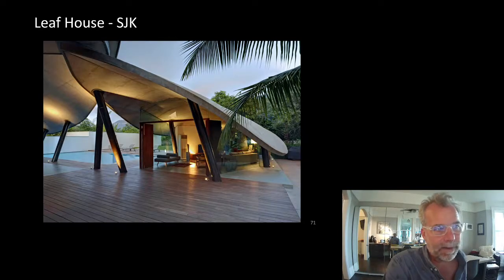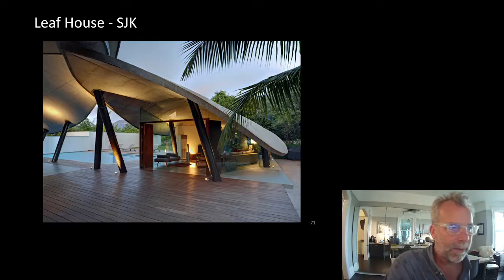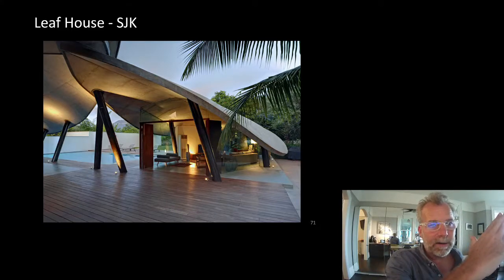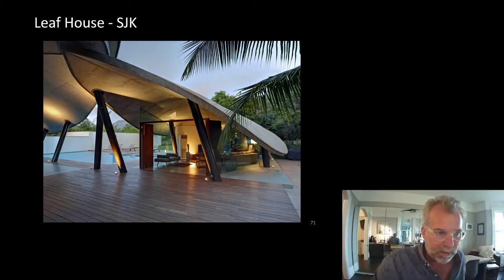This type of cast-in-place concrete doesn't have that problem, partly because it's curved, partly because it's so robust. So the challenge here is not a technical challenge. This thing is extremely robust. The challenge for this canopy would have been the formwork, forming and pouring. We've got to pour concrete on a slope and keep it from sliding out, so you need a very, very dry, very stiff concrete.